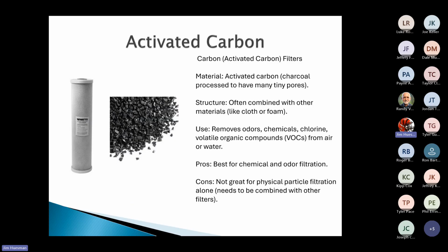And what we're doing is, it's more of a burnt coconut. Okay, it's burnt coconut shells packed in there really tight. And as that water is running through, that coconut shell is able to absorb all of that stuff. So we're able to get rid of a lot of those odors and the chemicals. And the big one is chlorine. So if you're living in a municipality where they're adding a little bit more chlorine than what you like, an activated carbon will get rid of a lot of that chlorine taste in your water.